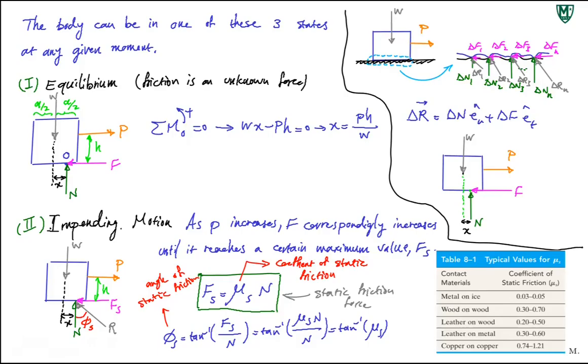In that case, you typically treat friction as an unknown force, and you have to calculate it in your free body diagram, put it there as an unknown. As I said, where the normal force is applied, you can actually find it if you find the moment about the right point, and somehow get rid of your unknown friction force, and not have it in your expression.